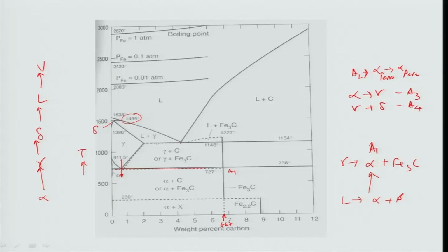So, that is why the dotted lines correspond to the equilibrium between carbon, pure carbon meaning graphite, and iron, and the solid lines correspond to equilibrium between iron and Fe3C. Okay. So, if you consider carbon, then this phase diagram should extend up to 100% carbon, not stop at 6.67% carbon, but it is not interesting beyond 6.67% carbon when you consider equilibrium between iron and graphite, even if you consider that.